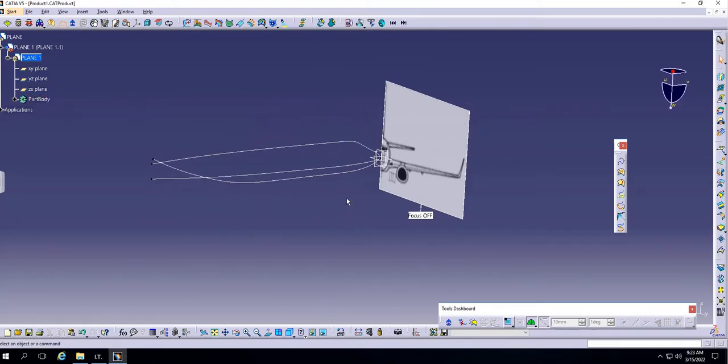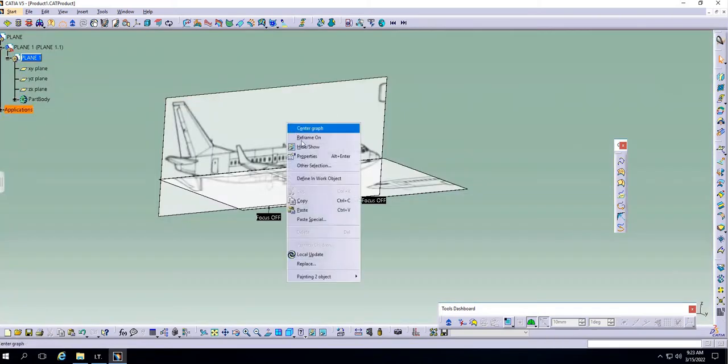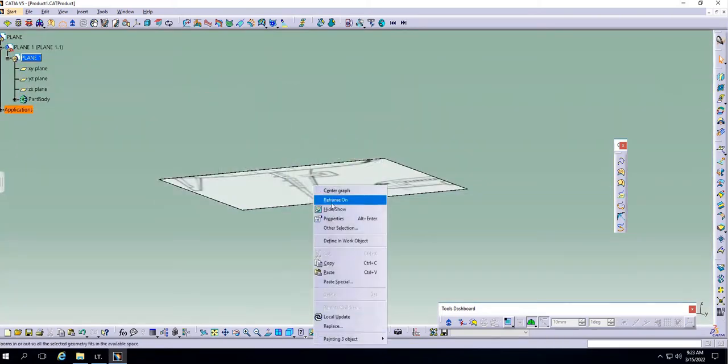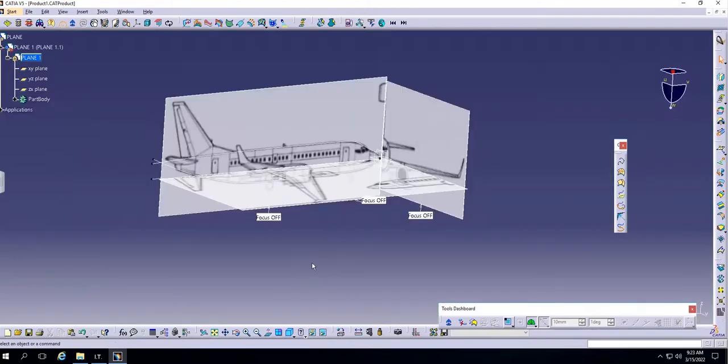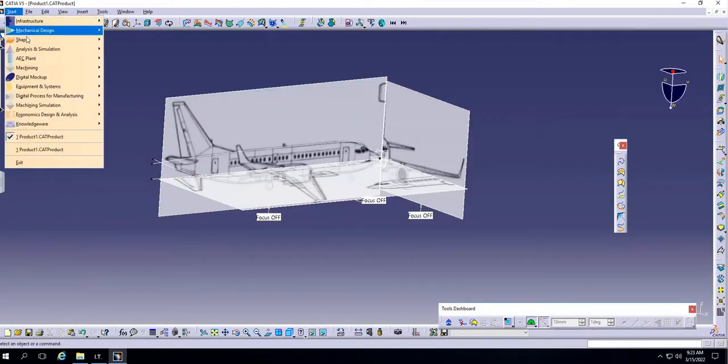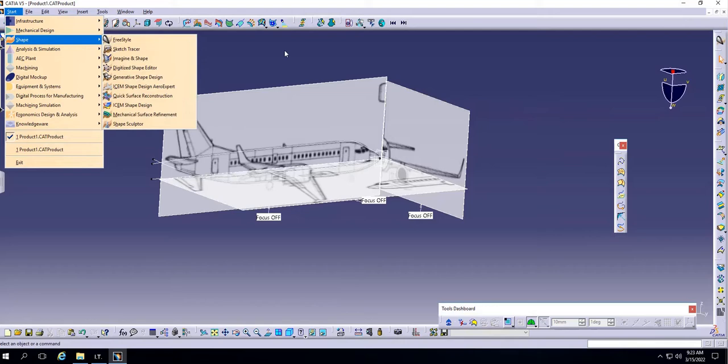So what we generally used was the 3D curve. So just to recap once again, in this video what we did, we simply tried making a sketch using part design feature. Then we realized that the sketch wasn't that accurate with respect to the frame that we had, and then we simply brought the 3D curve into action under the freestyle option, which is under shape design freestyle.